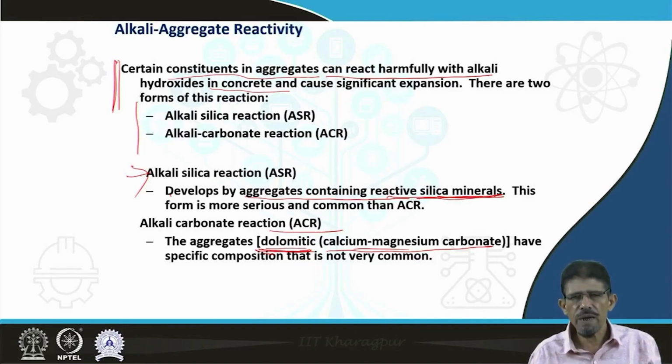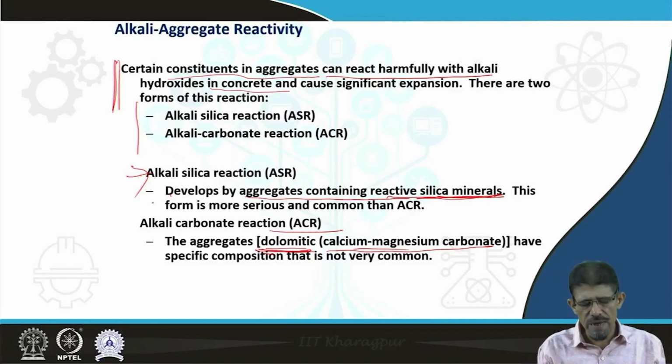If the limestone contains some dolomitic component and is used as aggregate of concrete, by mixing the aggregate with cement in the presence of water, then this dolomite is going to interact with the alkali present in cement and cause such a hazardous reaction. So one by one we are going to discuss.